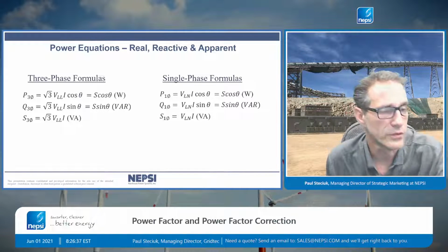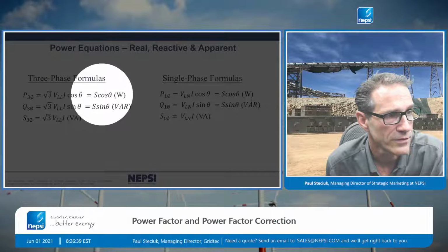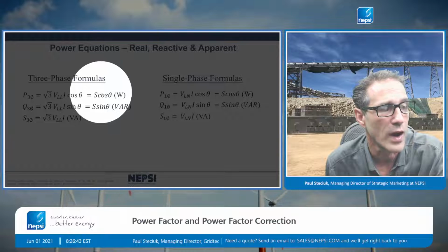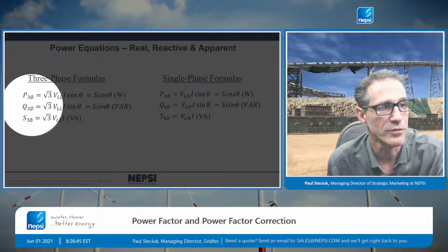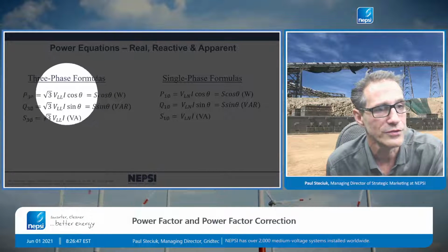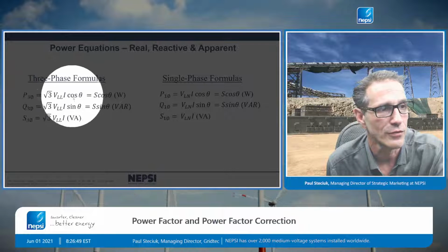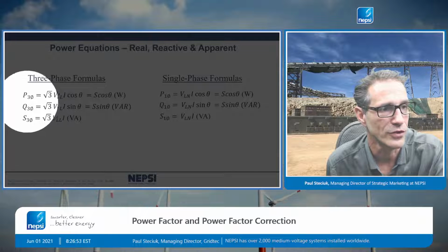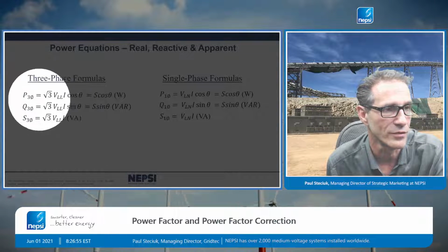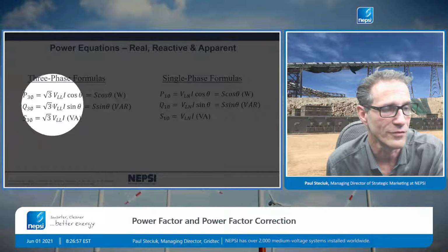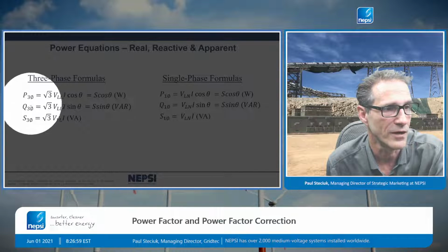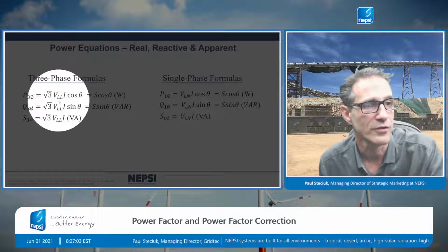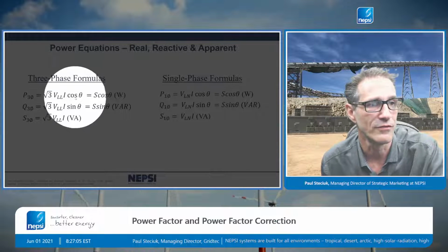And that's also equal to the complex power, all right, times the cosine angle. You can come up with the same value there in watts. So a similar value for Q. Always associate power with cosine, associate sine with reactive power, so Q with sine. It's a good way to remember it. Most often, whenever you're talking about reactive power, you're going to be using sine. Whenever you're talking about watts, you're going to be using cosine, those two formulas.